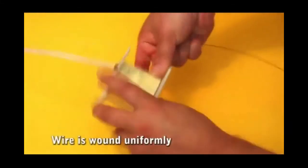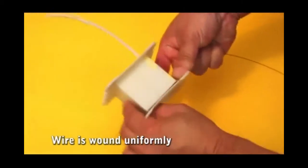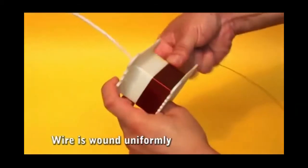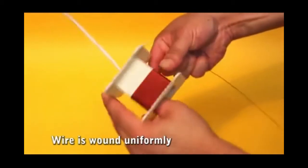Winding the wire. Wrap the wire of the primary winding from bottom to top, from left to right, pressing well and taking care not to ride one turn over another, with no spaces between the turns of wire. This is done in an orderly and neat way to fit all necessary turns.